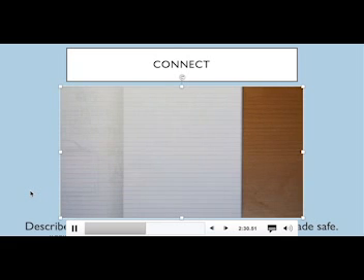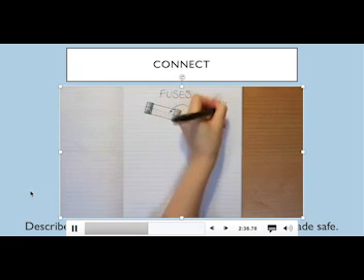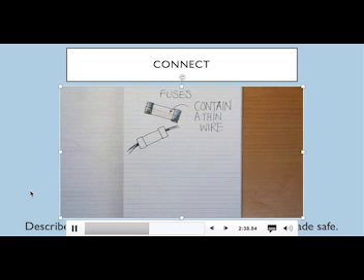Another way that mains circuits are kept safe is the use of devices called fuses. These consist of a thin wire with a low melting point. If a sufficiently large current flows, it will heat up, causing the wire to melt and blow the fuse, interrupting the circuit and cutting off the supply. And because the fuse is designed to melt at a much lower temperature than the wire used elsewhere in the wiring system, this safety measure can help to prevent large currents from causing wiring to catch fire.